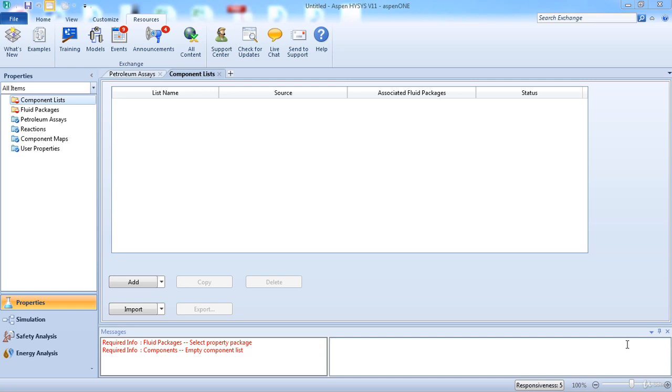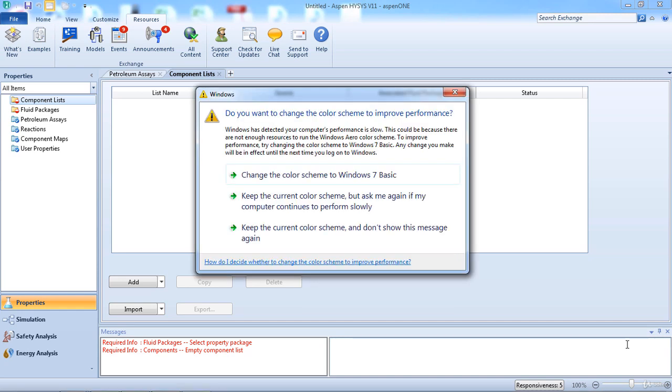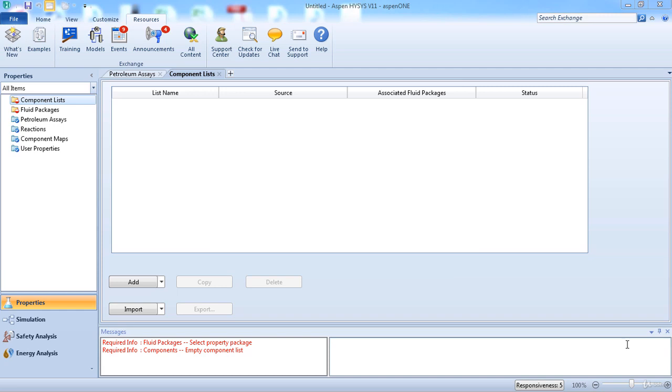In the case we have today, we need the water dew point to be negative 10 degrees Celsius at 6200 kilopascal. We will learn how to do that in reality by simulating a dehydration system using triethylene glycol to absorb the water. First, have a look at the gas dehydration document to see the drawing of the system.